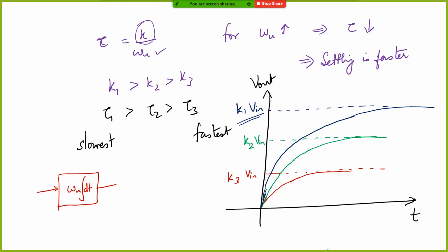Many times you will have requirements saying that this particular system has to settle within, let's say, 0.5 nanoseconds or 500 picoseconds. Now you have to build your negative feedback loop, designing each of these elements such that my accuracy is, let's say, 1%, which means about 5 tau. Let me just give that example and close this class.